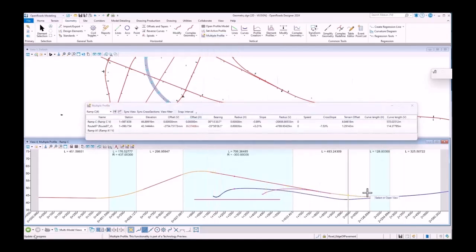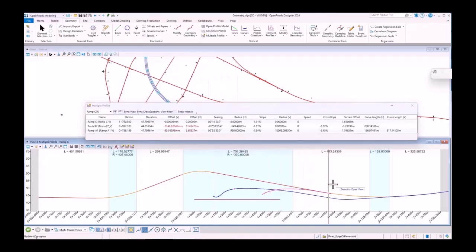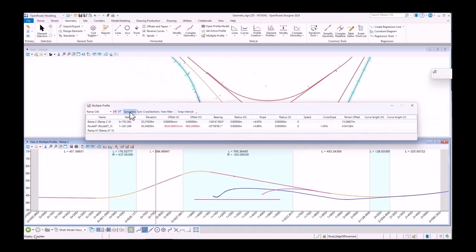It's got a new tracking and analysis capability in here, so as I browse around, I can see tracking across all of these profiles at once. In this case, I've got 3 profiles in there. I can turn on and off any of these columns of information that I want to see, and I can even have them highlight and tell me if it exceeds some criteria I established. For example, if I want to know if the delta vertical offset is greater than 150 millimeters, I could turn that on. And when it does show up as greater than that, it'll be red in the dialog.